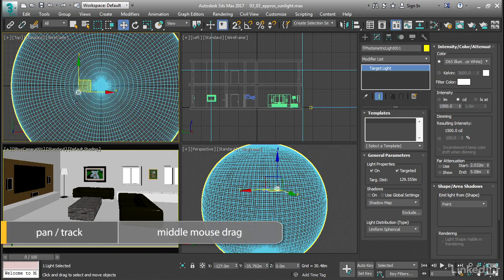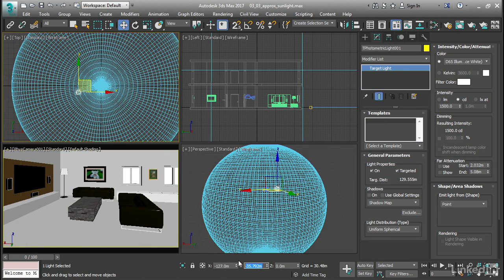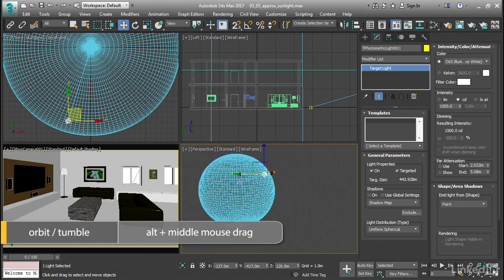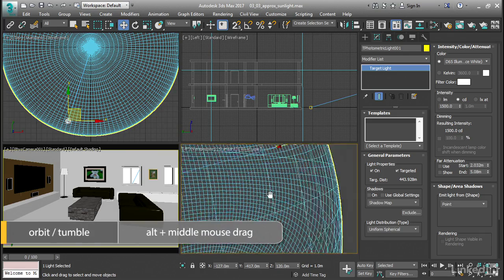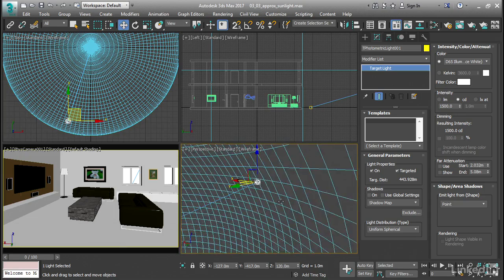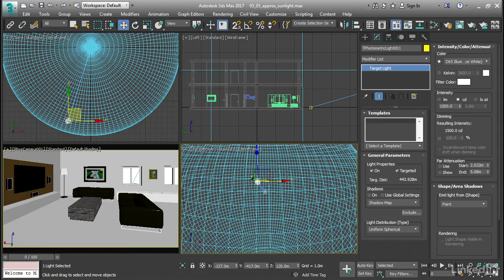Now it's pretty far out there. The Y value, set it to negative 417. And then finally, the Z value or elevation here, I want to be 120 meters above the horizon. And now that light is positioned pretty much in the same place that the sun positioner was. And it's just inside our environment sphere. If the light itself were outside that sphere, then the sphere would cast a shadow and the light would not be able to reach into the window.